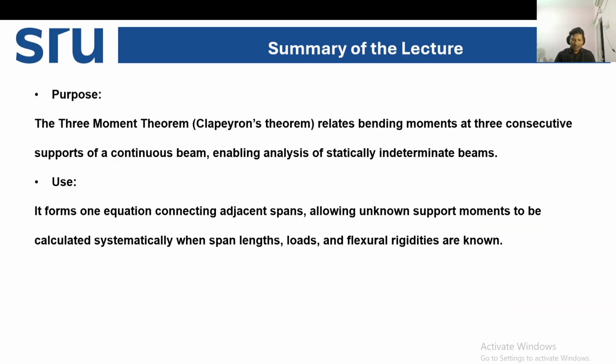So, summary of the lecture: what is the purpose of this three moment theorem? The three moment theorem is also called Clapeyron's theorem. This is important. Sometimes it is asked on the name of this scientist, that is Clapeyron's theorem. So the three moment theorem relates the bending moment at three consecutive supports of a continuous beam, enabling analysis of statically indeterminate beams.